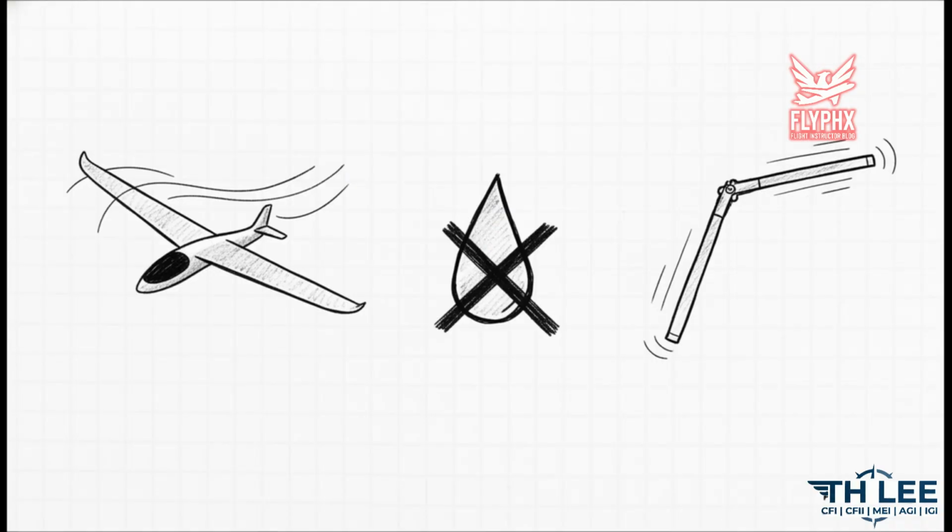The advantages of using these materials are just immense. First, composites allow for extremely smooth, compound-curved, highly aerodynamic structures that drastically reduce drag. This is exactly why sailplanes and modern aircraft like the Cirrus use them. Second is a complete lack of corrosion.